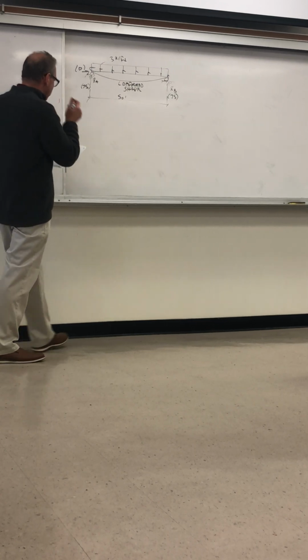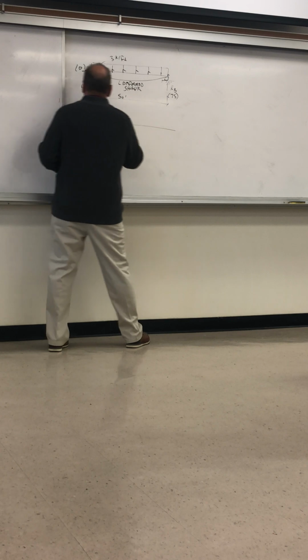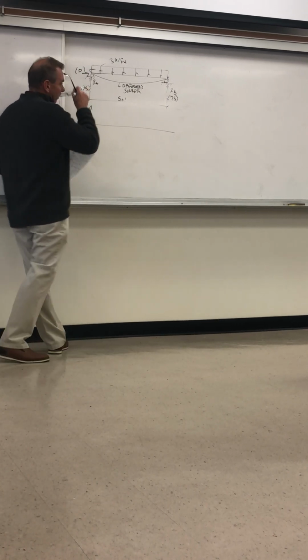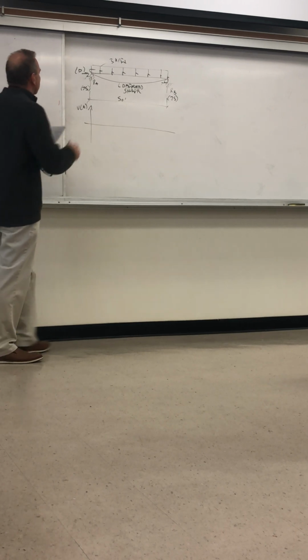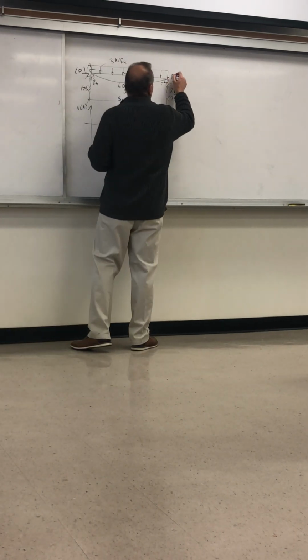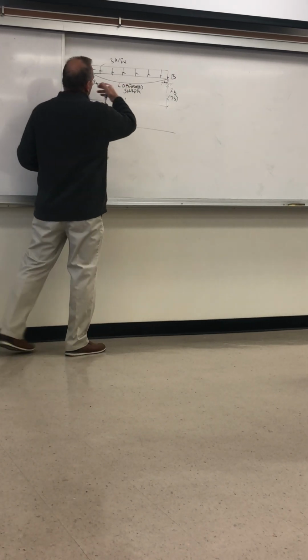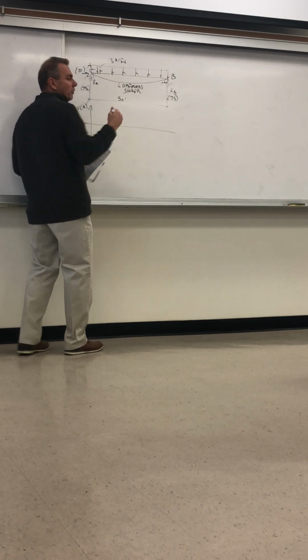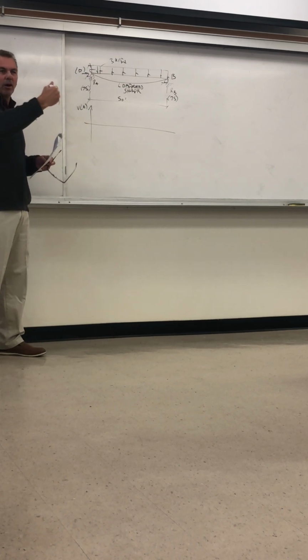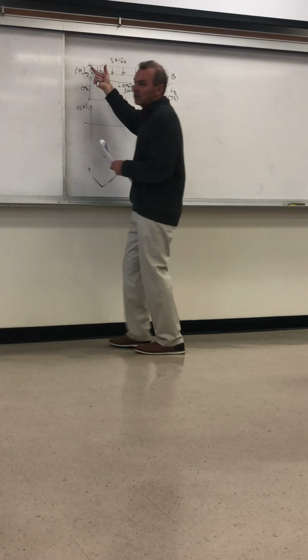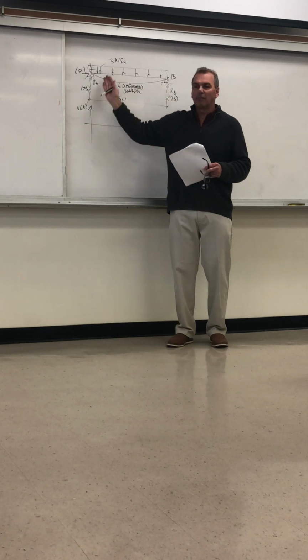The shear diagram in this case looks like this. First, this is A and B. When we first enter the beam, there's a force up when we cross over A of 75,000 pounds. That's the distributed load, but that takes time to add up, right? There's 3 kips per foot, but in the first, let's say, inch, when you just move into the structure, all it feels is that 75,000 pounds up. And then over time, it's minus 3 times any distance. But if the distance is 0, it's 75.